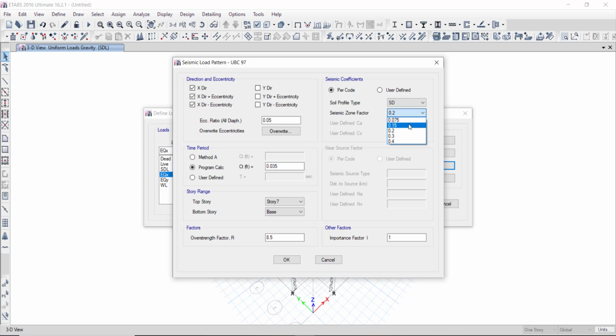So this is zone 1, suppose. Okay, this is all stories. We are making it 5.5. That's intermediate moment resistance frame, because this is zone 1, and in zone 1 in A and B, like we have 5 zones, so you can select any one of these.